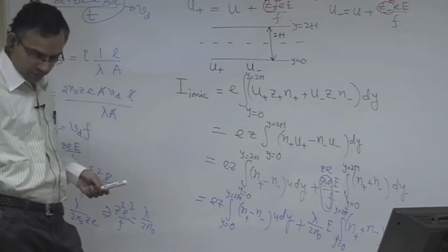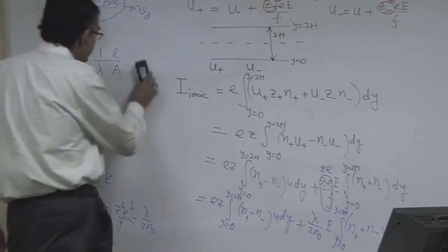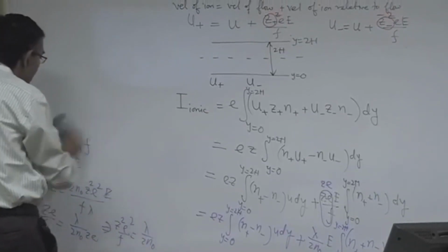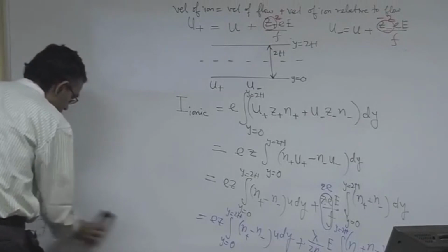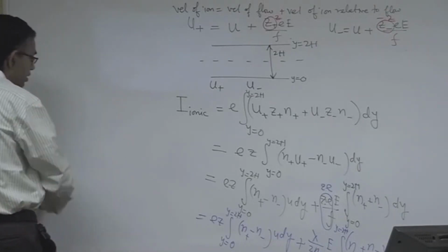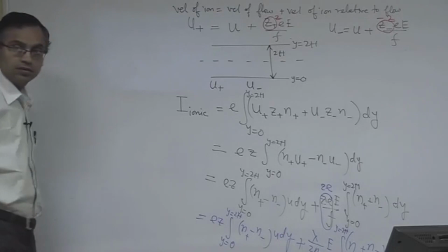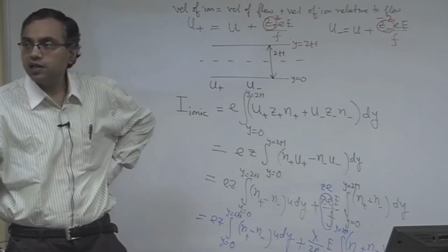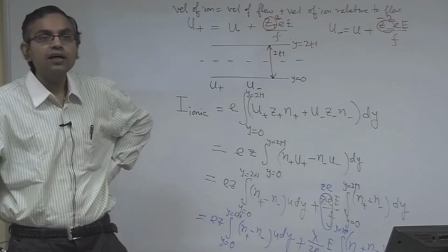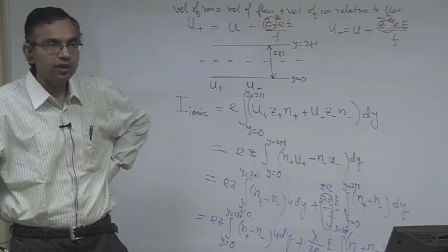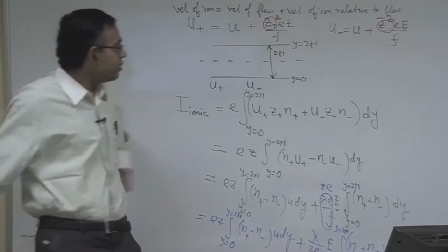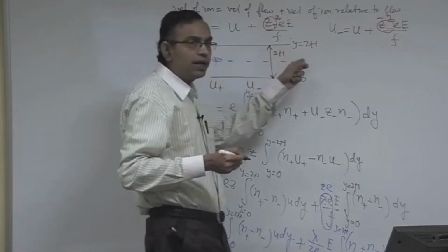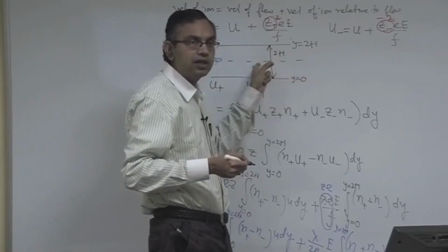Now the velocity field. What is U here? U is equal to U pressure driven plus U back electroosmotic. So here you have a pressure driven flow in the forward direction and backward electroosmotic flow because of the streaming potential field that is developed.